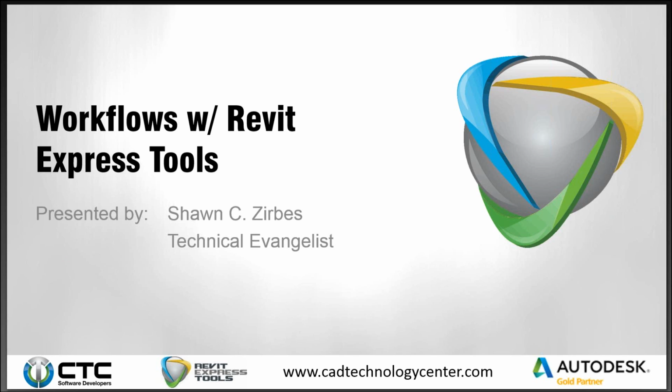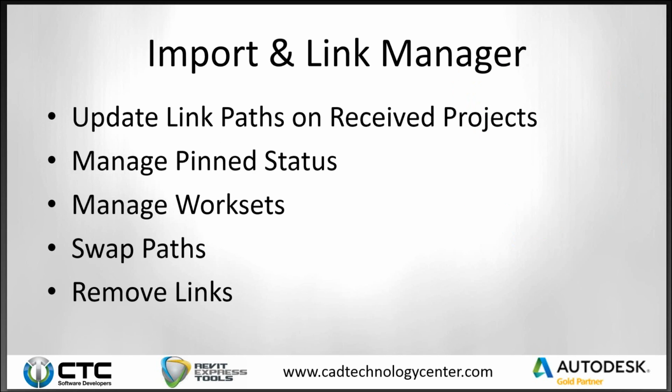week, which was the overview of Import Link Manager, just in case you didn't make last week. I'm going to breeze through it pretty quickly here. So it lets you update link tabs on received projects, which is something we're going to demonstrate specifically today. You can manage pin status of components. We'll talk about that one. Manage the work sets of objects. We'll talk about that as well. The ability to swap paths on, say, DWG, which we'll talk about in the next presentation, and how you can remove links, which is something we'll touch on a little bit today and dig into a bit more next time around.